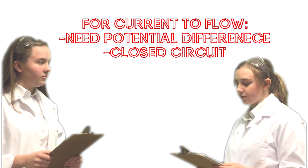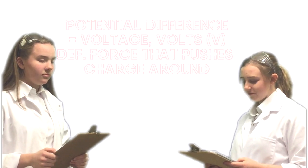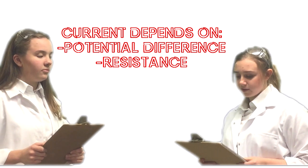Current will only flow through an electrical component if there is a potential difference and the circuit is complete. Potential difference, which is measured in volts, is the driving force which pushes the charge around. Resistance is anything that slows the flow down and is measured in ohms. The current flowing through a component depends on the potential difference across it and the resistance of the component.